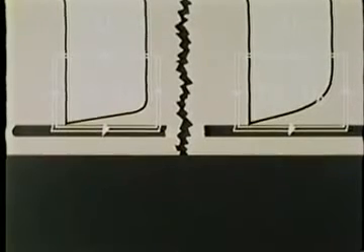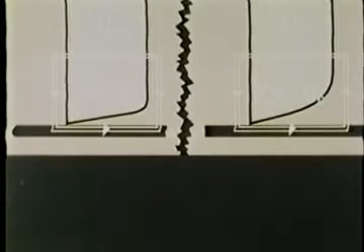The total amount of vorticity within each contour is the same. Because there is no vorticity upstream of the plate, and because the circulation per unit length along it is constant, we conclude that all of the vorticity is generated uniformly along its length. Upstream, 95% of the total vorticity is contained within this area. Downstream, 95% of the total vorticity is contained within this area.